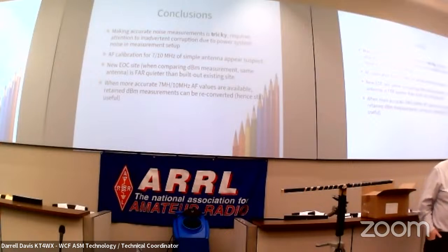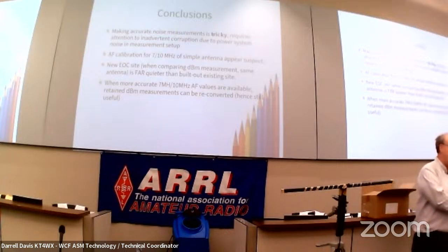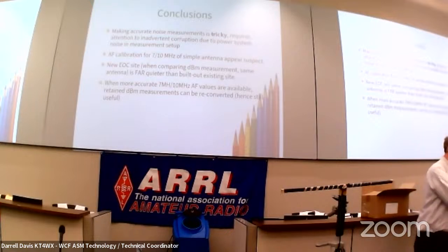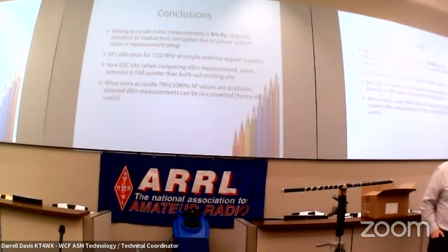But it takes an enormous amount of filtering to do that because the generator is an end-fed transmitter operating with the extension cord as its antenna. And you've got to filter, filter, filter, filter. It's got a ground connection for the other half of its antenna system, and it uses the extension cord as a 100-foot long, wonderful multiband end-fed antenna, common mode. So the noise engineering is quite a lot of work to try to solve your HF problems. I think there's one EOC that couldn't even operate on 2 meters.